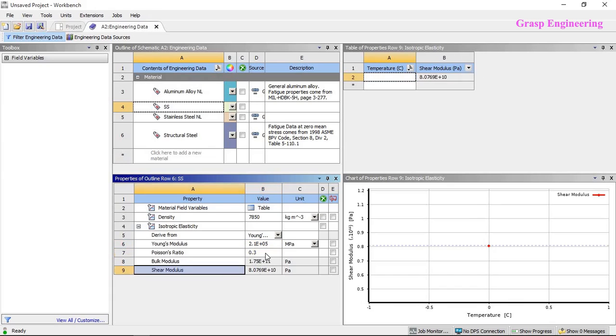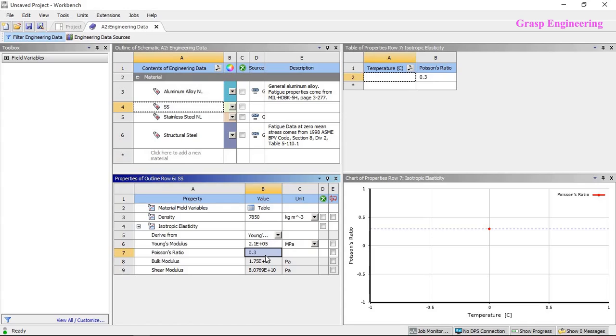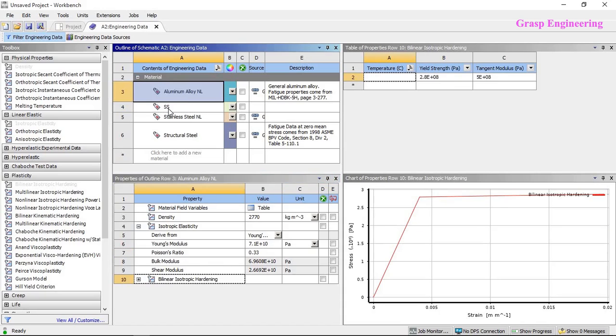Basically, if you have a Poisson's ratio of more than 0.4, you just need to say that this is a non-metallic gasket, or a plastic or others, which may have a higher Poisson's ratio compared to steel or linear material. Then let's see, okay, SS.